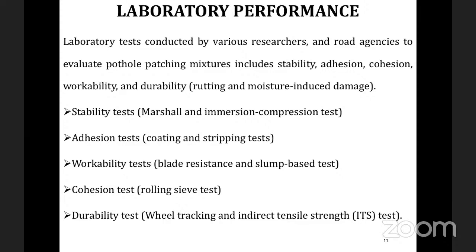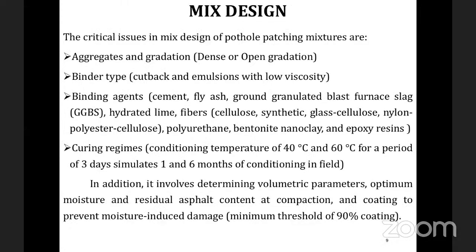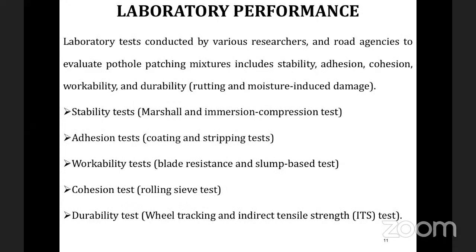And the next one is the ITS test in order to assess the moisture induced damage. That is indirect tensile strength, based on the TSR, tensile strength ratio. This is like the coating percent I told, 90%. Like that in ITS also, we can go for TSR, that is tensile strength ratio. That is nothing but the ratio of ITS of the sample in dry condition and wet condition.